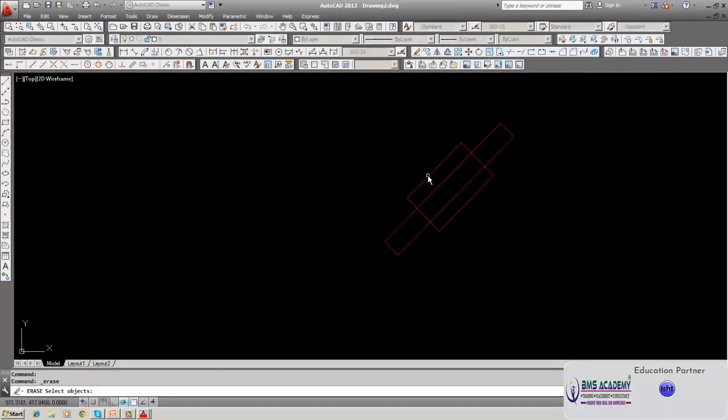This is actually a block, but it is a drawing too. I have explained the paste as block. No, it is identical to that. So the same thing you can do by pasting a drawing on any other drawing as a block. You have to use the command copy clip, and then paste. The same type of work is done here by the computer. Okay.